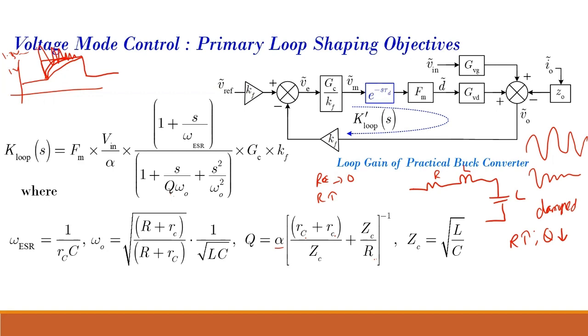In this context, we use the quality factor, and that is also why we use the concept of phase margin. Your quality factor or your damping are closely related to your phase margin. For a second order system, we have a relation between phase margin and Q and zeta.